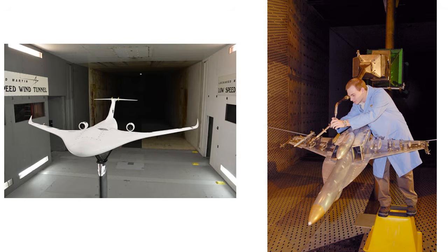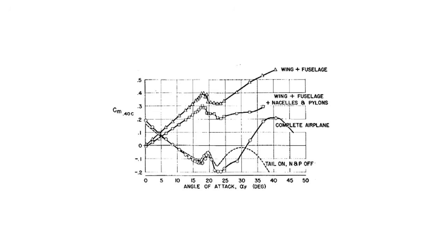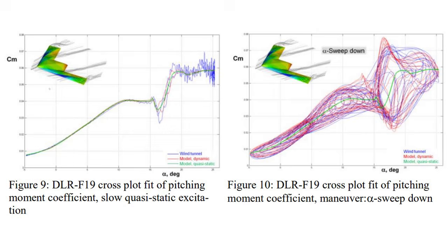tests. Before any professional aircraft flies, any analysis models and results must be verified. If there is a significant difference in results, especially in the stability characteristics of the aircraft, it's obvious why this would be a major issue when investing the time and the money into a maiden flight. To ensure that the aircraft experiences the expected static and dynamic stability characteristics and generates the expected forces and moments during all stages of flight with all control surfaces being used at one point or another, wind tunnel testing is